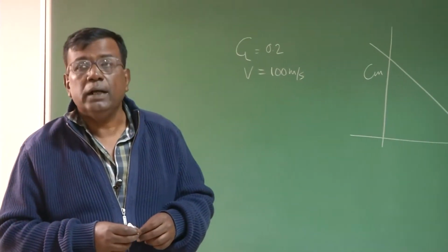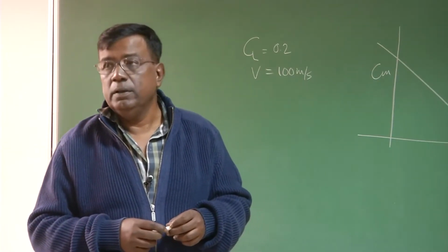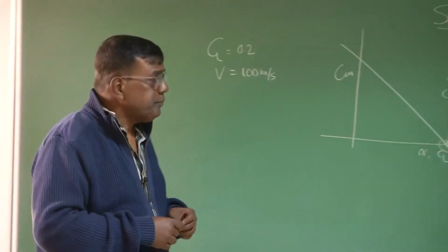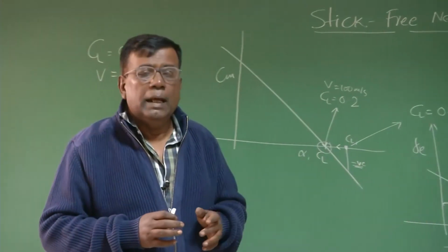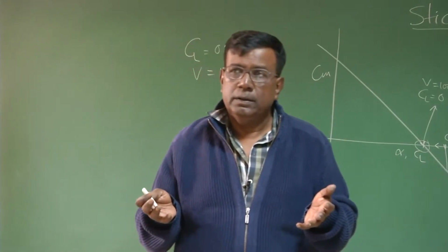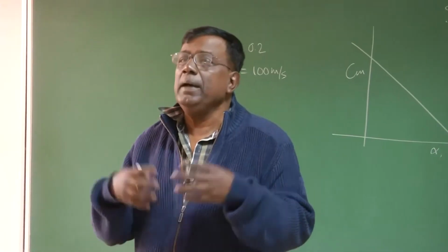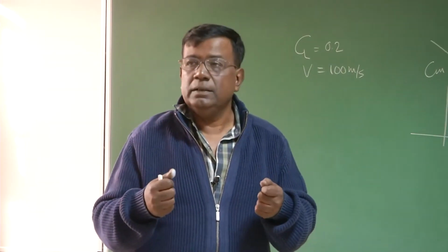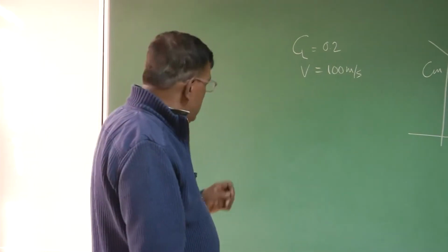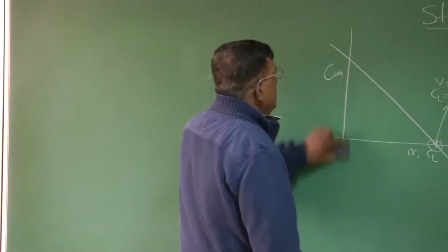And you need to use that concept of stick force to define a stick-free neutral point. But be very clear, if you see my module, the airplane has only a neutral point. It is the stick-free neutral point we are defining so as to develop a mathematical model which will help to give a feel for the pilot. That's all.